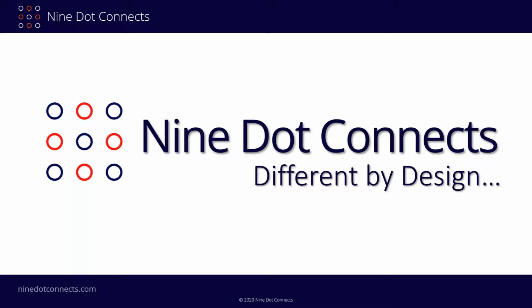So there was a good question here, and I do agree with this one. How do you communicate through parameters to someone purchasing which parameters are essential? For instance, a 10K resistor must be 0.1% and 25 ppm Tempco. I know that they're in the data sheet, but how would they know that they are design critical? I think it's a really great question, and I probably should have spent a little more time talking about this.